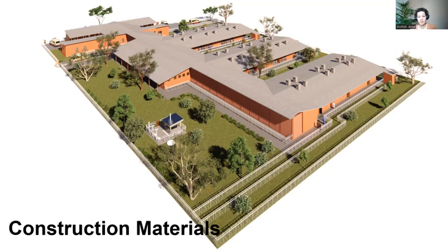For the roofing, a structural concrete slab covered with a corrugated metallic panel has been proposed. A ventilated air gap has been considered between the metal finish and the structure to decrease the temperature of the roof during the summer days. For the roof and the exterior paving, lighter color should be preferred to reflect as much as possible the solar radiation and prevent both the indoor overheating and the heat island effect outside the facility.